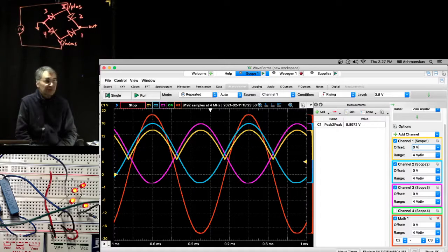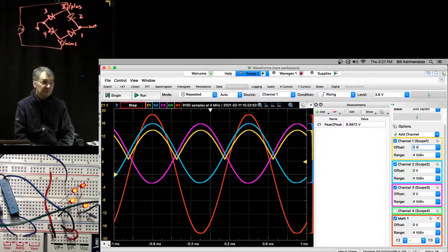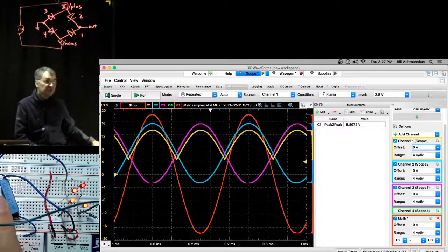So you don't have to do this, but if you're feeling really super duper ambitious, I call it a super duper extra credit option, you can build this full wave bridge rectifier with the EE board using 4 LEDs, and you can use a pair of sine waves, 9 volts, 180 degrees out of phase. Joe's didn't use the blocking capacitors.